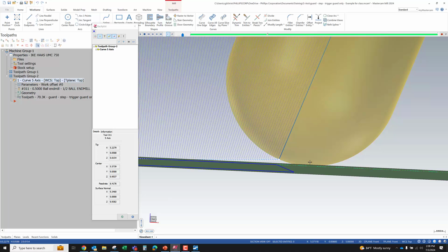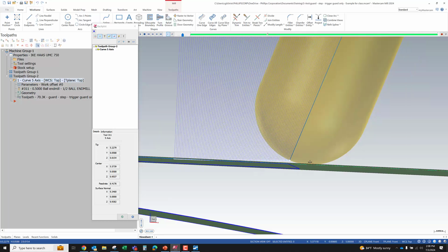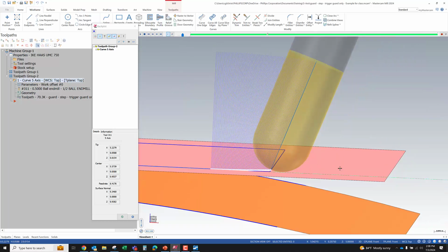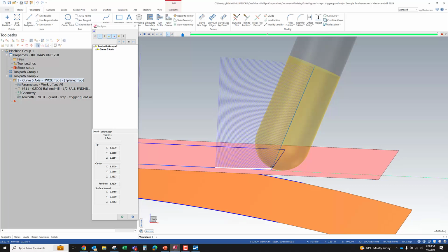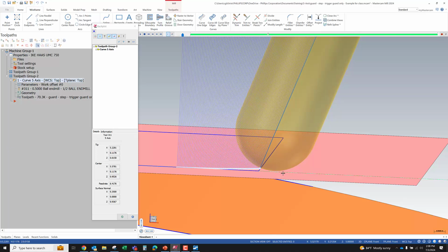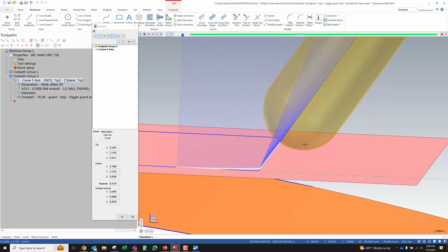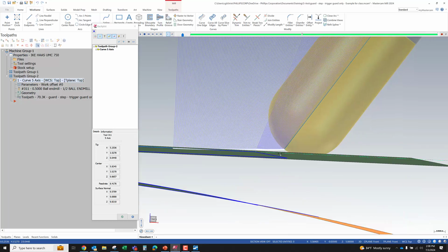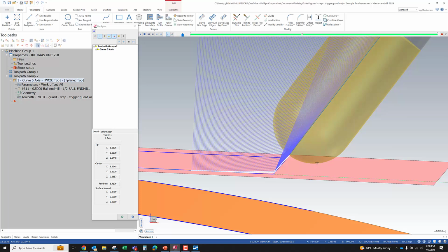So what that requires is a surface, like I said before, that's more like a runout surface. You want the surface that's part of the compensation of the toolpath to go and extend, at least, in my opinion, by the radius of the tool beyond what you're driving, so that it can always maintain the proper tangency and you don't see the tool all of a sudden drop because it reached a place where there's no surface here and it's like, oh, I can get closer, there's nothing to hit, and so it'll drop, right?